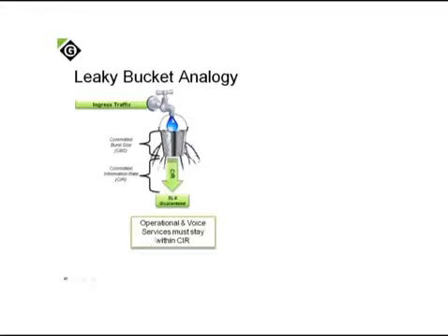Now, why this is important is that operational SCADA type traffic, teleprotection traffic, and voice services absolutely have to stay within the committed information rate. We do not want them to go beyond those bounds, because anything beyond the committed information rate can be thrown away. It's discard eligible. So that's the reason why it's important.